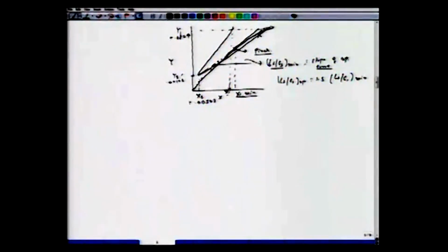So let's come back to these calculations from the previous values for G1, the flow rate of the gas. One can determine Gs first as G1 times (1 minus Y1), which, if you calculate with 0.01, you will get 0.01051 kilomole per second.